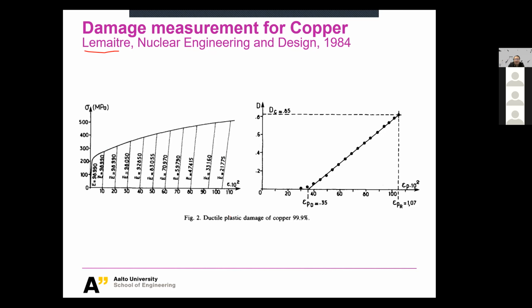And that is what he found. When you just do a tensile test, when the ductile fracture is developing, so when you have many voids generating, we see there's a degradation of the material. So we define damage as an irreversible degradation of the material. And this degradation is reflected in the stiffness, the Young's modulus. Basically, when you do a test and you load and unload and load again, you will see the stiffness, the Young's modulus, getting smaller and smaller.